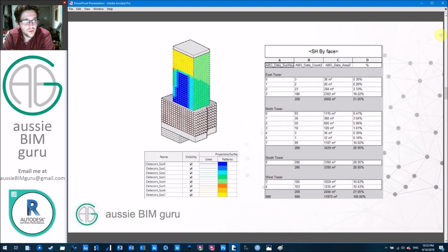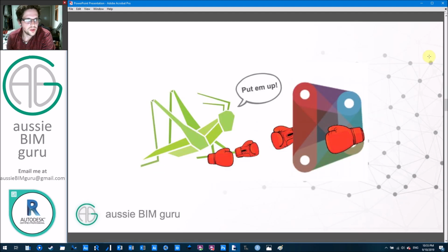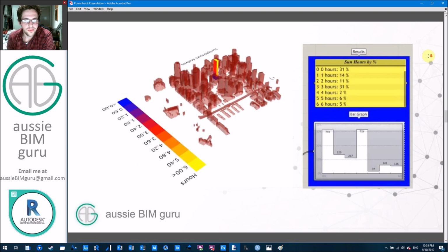In Revit, what I originally did was filter all the elements in order to override their color, but Grasshopper can do this a lot more directly, built into a package called Ladybug. So Grasshopper's definitely going to do a better job. It's going to look a little bit like this. As long as you have some context in Rhino and a building to test it upon, we're going to set up the ability to generate this study and also generate these results.